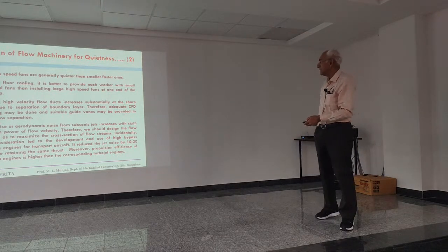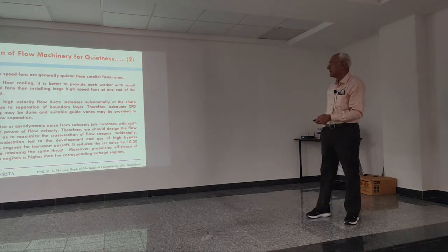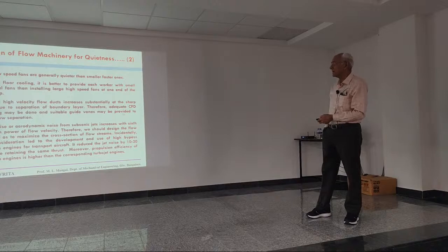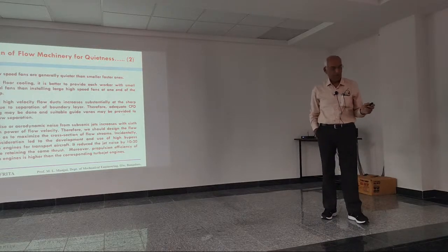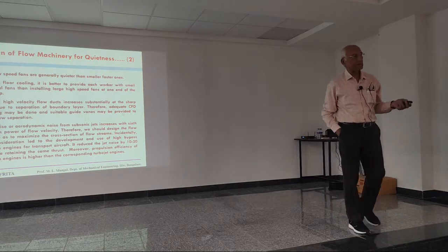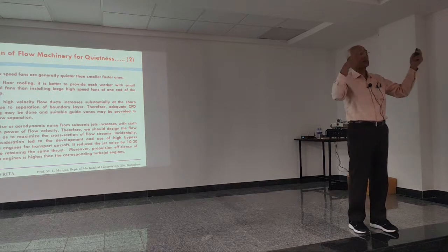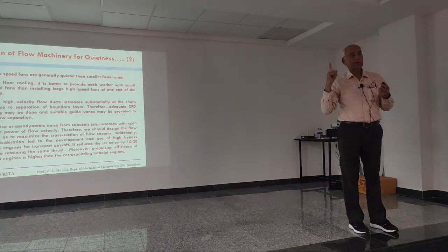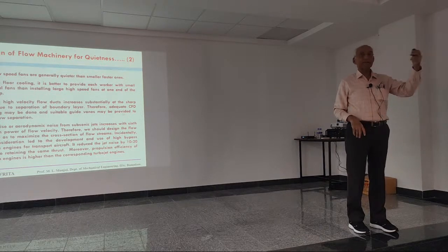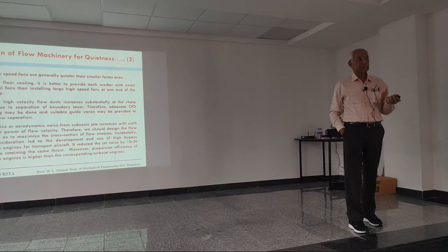Okay. Noise in high velocity flow ducts increases substantially at sharp bends due to separation of boundary layers. Therefore, adequate CFD modeling may be done and suitable guidelines may be provided to avoid flow separation. So basically, all noise is produced when the boundary layer separates or a free shear layer is formed. So you have to make sure that the flow remains attached to the surfaces, and then you will find not only will noise be less, the losses that happen because of eddies will also be less.